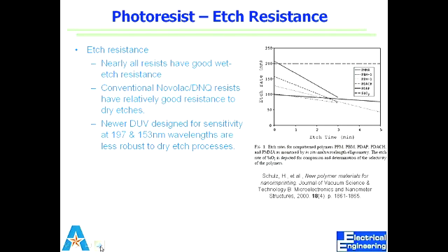Any other reason why you would want it? Yeah, the one with lower slope also. Lower slope. The etch rate doesn't change over time, right? So the etch rate stays constant, because if all of these are good because their etch rate is going down, which is good, right? Because with time, we want it to become resistant to etching. So again, which one do we want to use, the one which has lower slope or higher slope? Lower etch rate and lower slope. And why do we call it lower slope? Because these are going down.